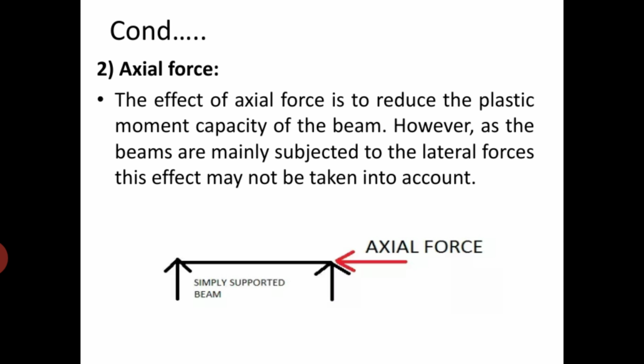However, as beams are mainly subjected to lateral forces, this effect may not be taken into account. So generally the beams are mainly subjected to lateral forces, hence the axial force is neglected, and it may not affect much. If present, definitely it affects the plastic moment capacity.